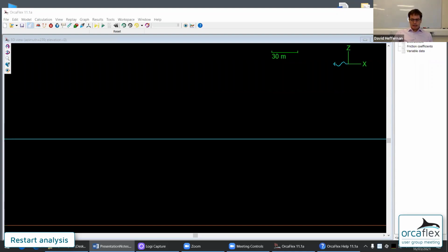The input data can be modified in a restart analysis, and that is what really gives it some power. Without that capability, the feature would be a little bit useless. It would just be like extending a simulation. So because we can modify data, we had a goal that the input data files for restart analyses just contained the data which had been modified.